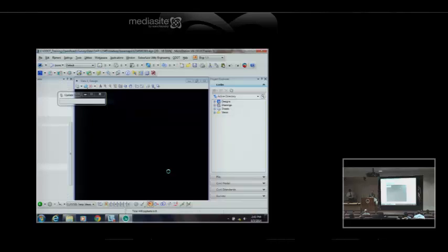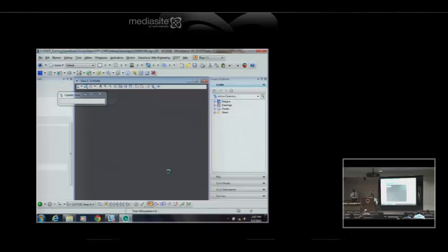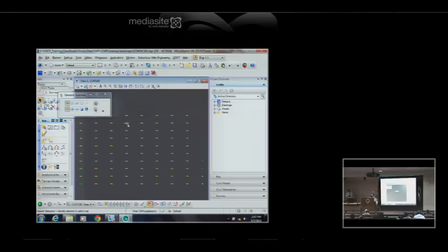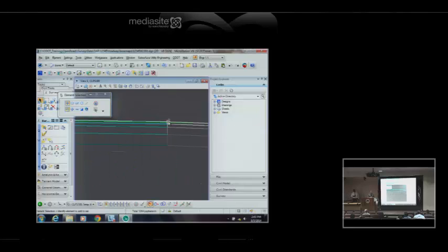I'm opening a cross-section file that's extracted from the model, and I just dumped them out there with a GeoPack cell, so it's not in a sheet format. It's literally what it sees in the model. And that subgrade line, I did not have that defined at this point. So at this point, it's just the layers and cells as line strings.